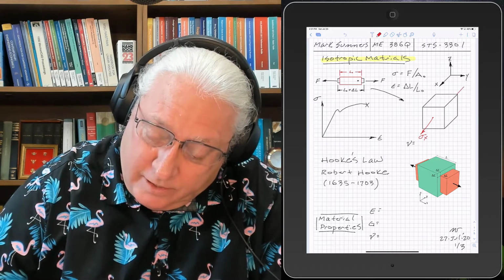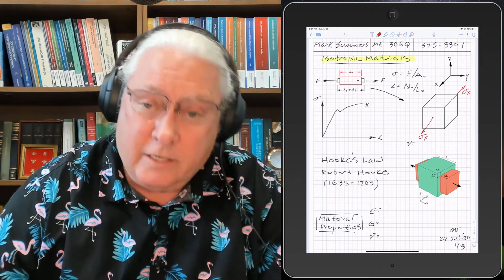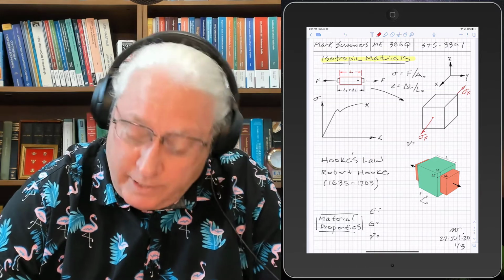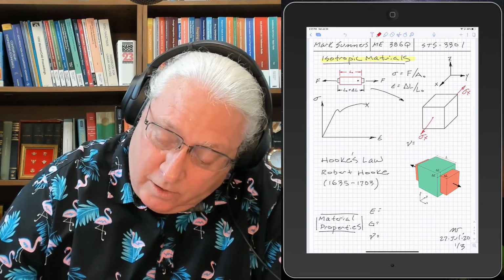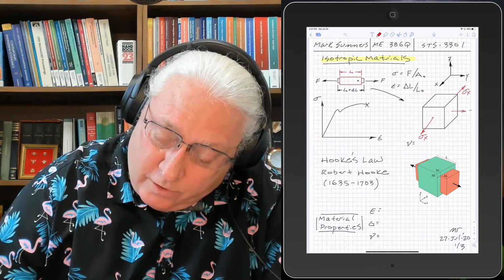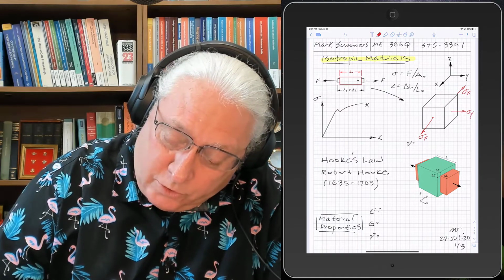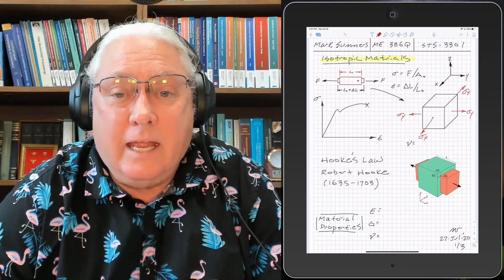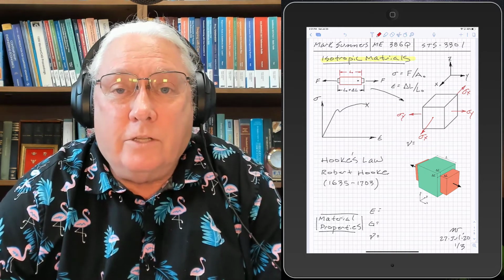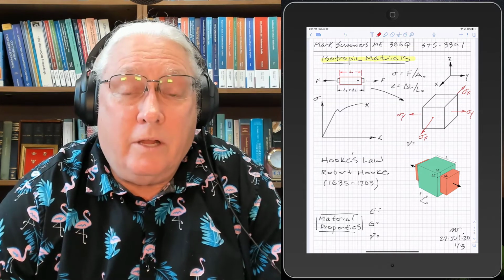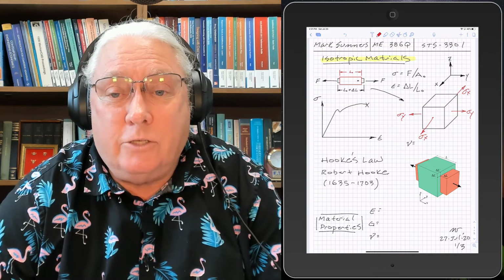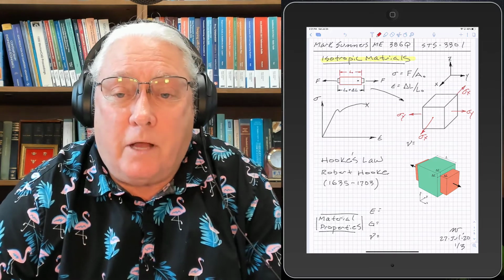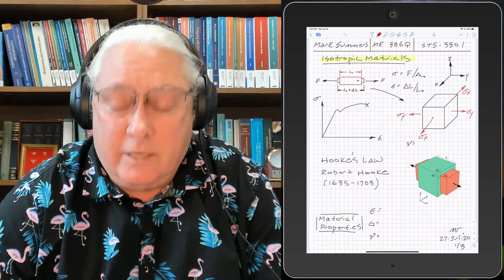in the x direction. Since we're pulling on both ends, it's in static equilibrium, so it's just sitting there. So we've got a sigma x going this way. We've got a sigma y, normal stress in the y direction. In the tensile specimen case, there is no force in the y direction. But we could have, and we usually have, a situation where we're pulling in multiple directions. So we're going to define all the different stresses that are possible, not necessarily the ones in the tensile test.